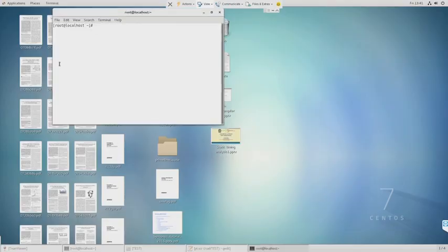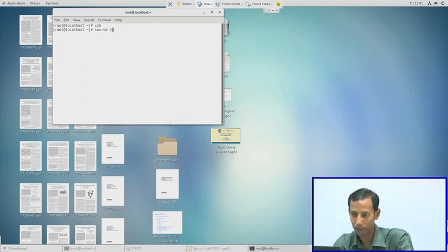Okay, so now we are moving to the demo on PrimeTime. To start PrimeTime, we have to do the same thing again: csh, then source the .cshrc file where we have written all the path information about this software.